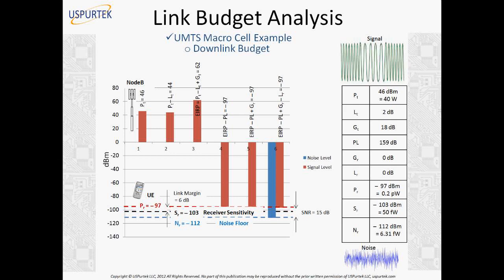Now 8 kilometers is okay, but if our signal level is not right, then we may have to reduce the cell size, or if we have plenty of signal, we may add to the range of the cell. It may be more of a business decision at that point: how much investment we can put into building cell towers, how many more cells we can deploy, and what the revenue from the users will be. So here we may have to make some adjustments.